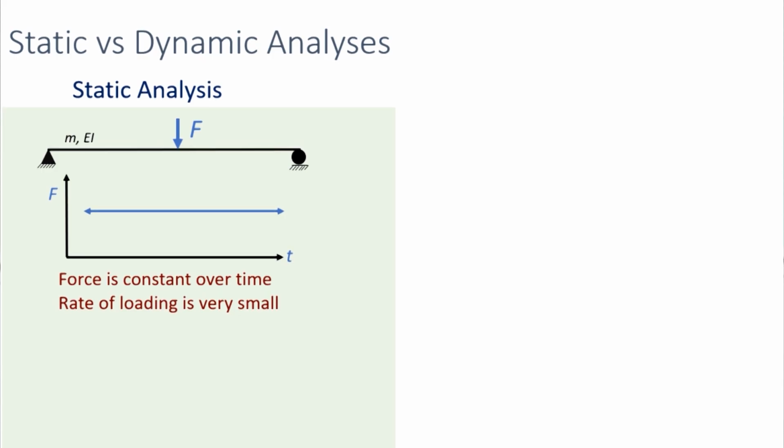In static analysis, it is assumed that the force is constant over time. So this assumption is valid only when the rate of loading is very small. In such cases, the variation of forces over time will be very insignificant and we can treat it as a constant force.